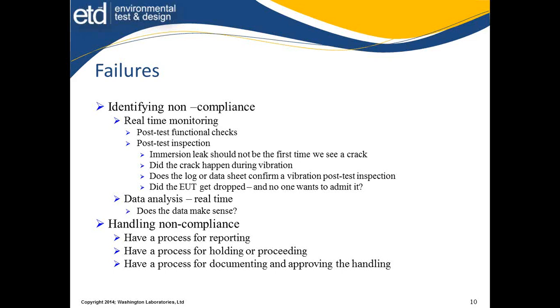Why did that crack appear? Did a crack appear? Looking at these elements is very important to us, and the test people have to take care of this. Does that vibration sensor or the accelerometer for responses get looked at? When we do a pre and post test sweep to determine if things changed, does anybody look at all the lines to say it stayed the same? They should. Did they record in the log that they did?